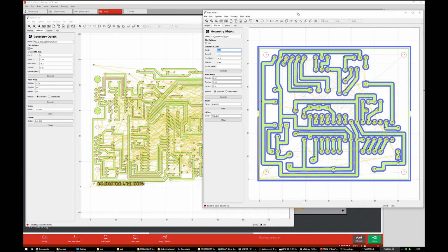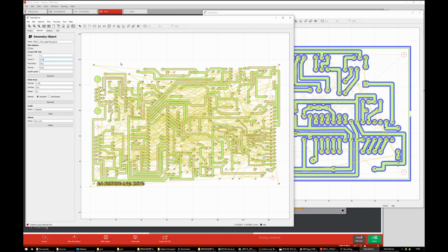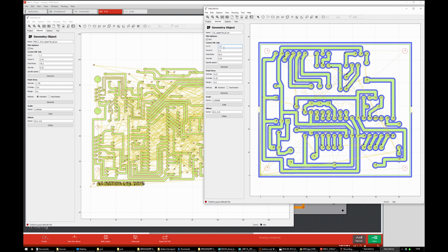Holes in the tracks won't really affect the electrical performance, but it's going to make the board more fragile, because some of these tracks are going to be detached from the body of the thing otherwise. So where the top and bottom layers cross over, there's a few points where that happens. Anyway, 1 millimeter in the negative Z is what I go with.